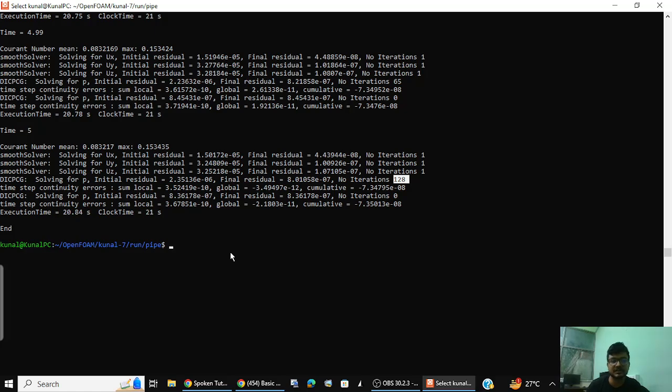First, just to summarize, was the grid independent study, wherein you refine the grid such that your result is grid independent. You try to balance your grid. You mention some zones, that in this zone I want to refine more, and in that zone I want to refine less. It depends on the gradient of the parameter that you are examining, and many other parameters. We'll be discussing it a little more in future. For the time being, this is about grid independence, and the run time is mainly applicable for transient solvers. For steady state ones, we need straightaway iterations.